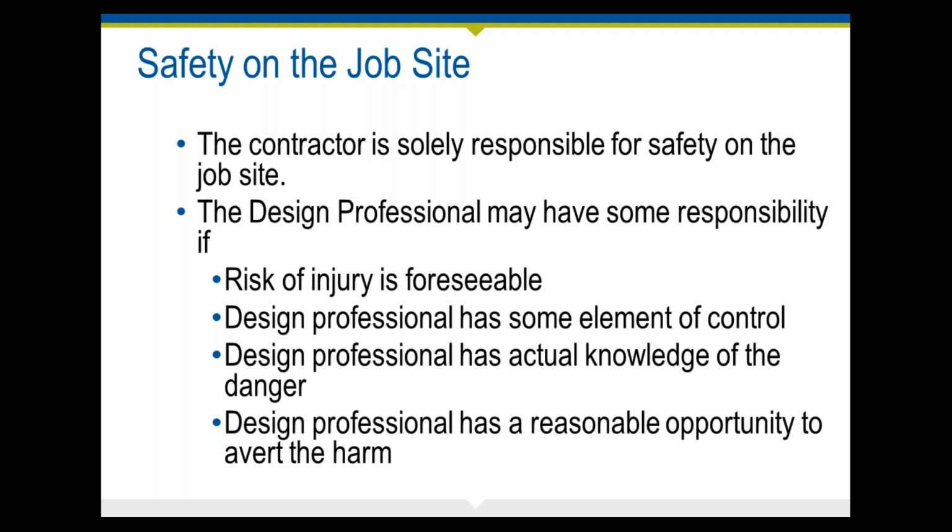You may be able to notify the superintendent that indeed you think that there is a trench box that is required at that time and place. And you, as a design professional, actually have actual knowledge of that requirement. It is pretty common that indeed, if there's an excavation that is deeper than a certain number of feet, you need a trench box. And then finally, you need to have a reasonable opportunity to avert the harm, meaning you need to be able to look at the site, look at the condition, and inform somebody about the dangerous condition.